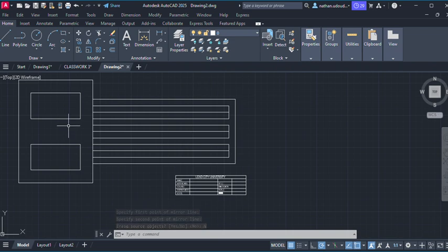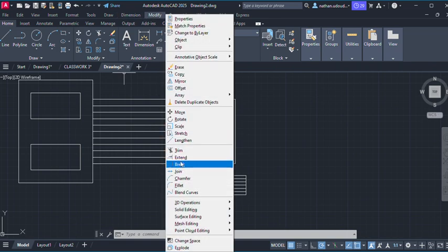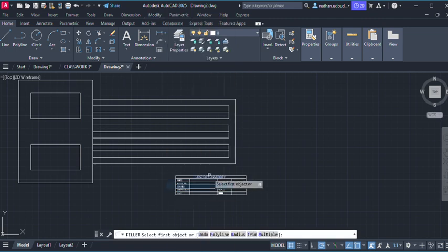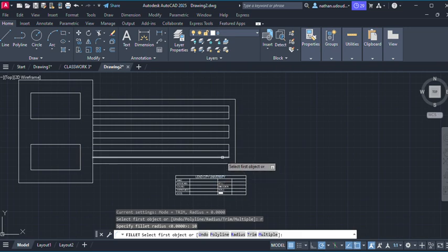So now what you are left with is your fillet. Okay, so for this particular point, what is your fillet? You pick your fillet tool again. You come here. Now what is the radius of a fillet? You take radius and then enter. So the radius of a fillet is 10. So 1, 0, enter.